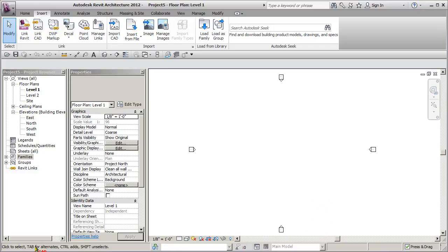Okay, then we've got our status bar, which is almost like a help menu. If you hover over something, look what happens down in here in our status bar. Okay, so if you hover over stuff, it'll actually give you information. It doesn't do much for you when you're up on the ribbon, but if you're inside of here and you hover over a door or a window or anything, it's going to tell you. So this is almost like the command line in AutoCAD. It's a one-way command line. It's Revit talking to you, but you don't get to really put the information in. You have to put your information in up over here. Okay, we have some stuff over here with work sets, etc. So we'll talk about the status bar and that as we move along.